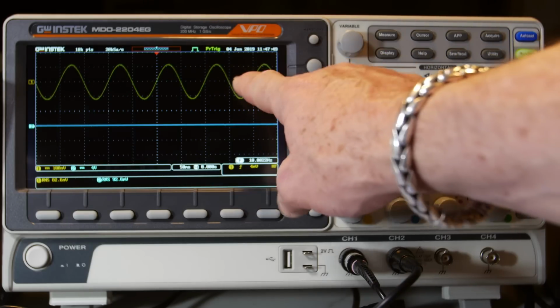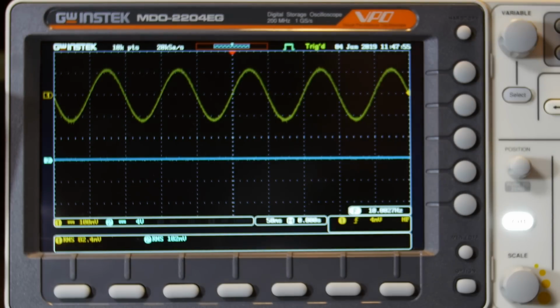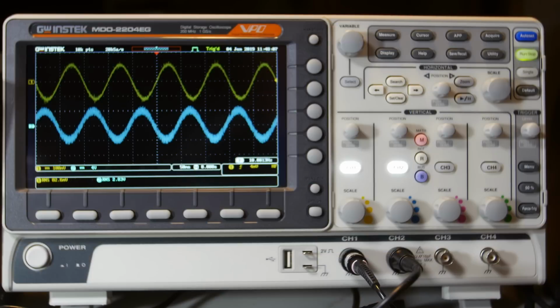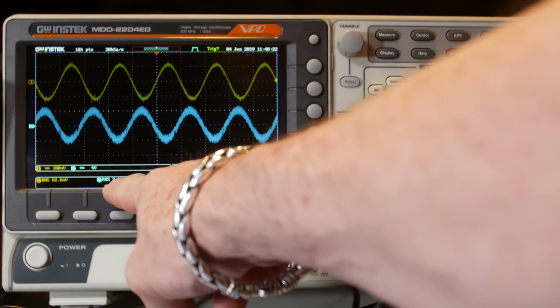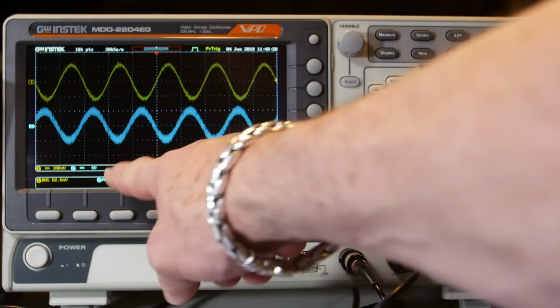Okay, here's the input. Let me turn on the power supply again, and okay, it's up to 31.6. You'll see the output click on. There it goes, clicks on. So this output is set for about, I have 82 millivolts going in and 2.8 volts on the load. And roughly, let's just say that was 3 volts.